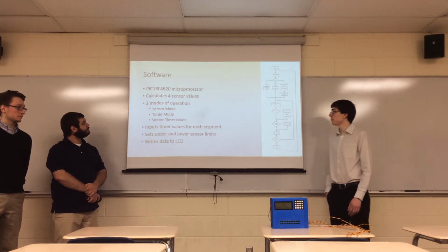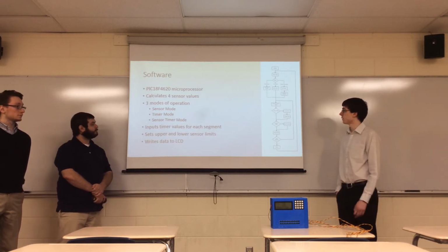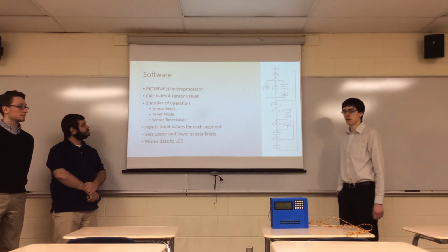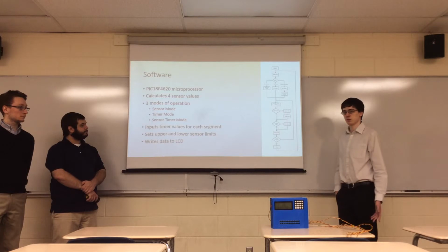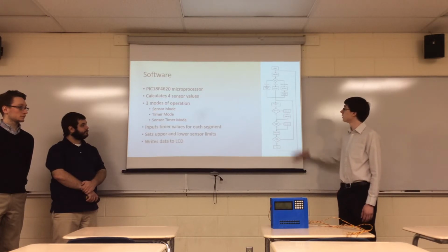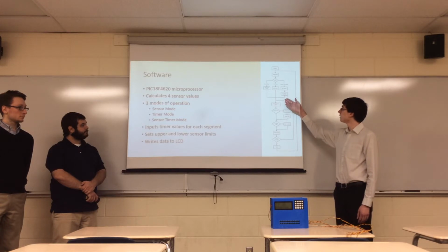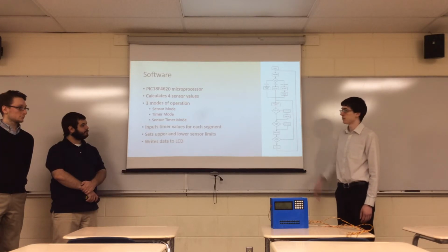So the software, we use a PIC 18F4620 microprocessor. The PIC, we program it in C, and in it we have this flowchart here, which covers the main function and how we move between different stages, including selecting different modes between sensor mode, timer mode, or sensor timer mode.